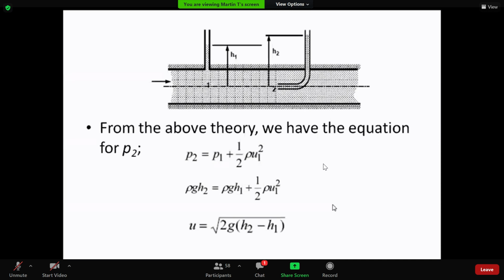Now at point 2, the distance from point 1 doesn't have to be big, as long as you're coming from a moving fluid to the beginning of the stagnation point; it can be close. At that stagnation point, you put an L-shaped tube and face it in the direction where the flow is coming from.